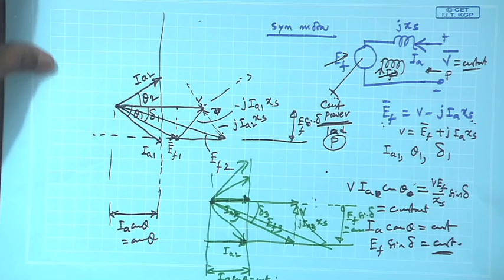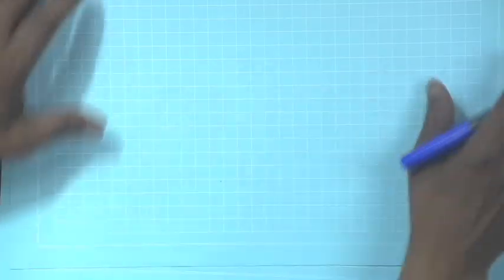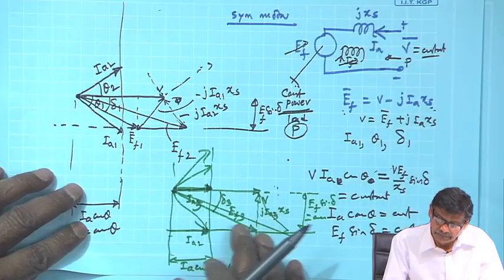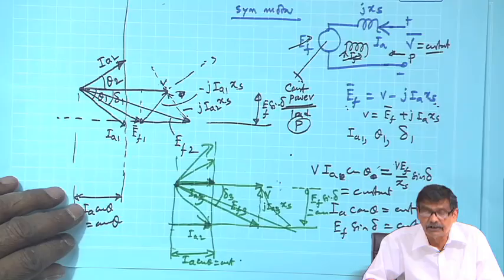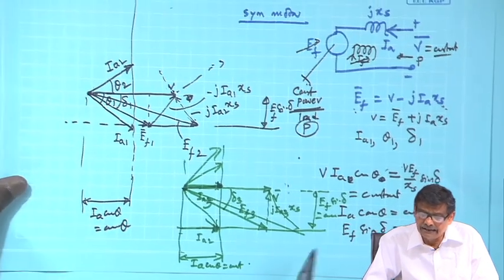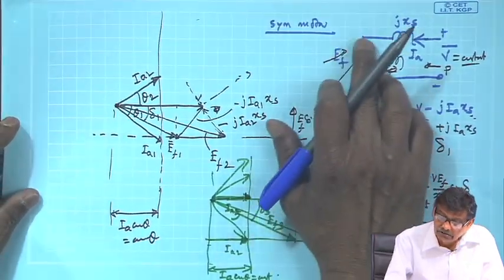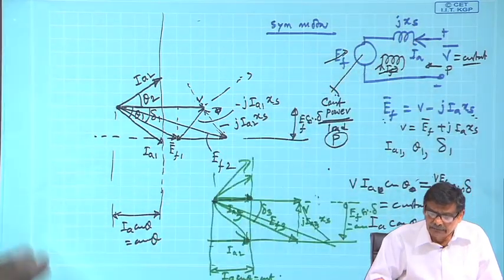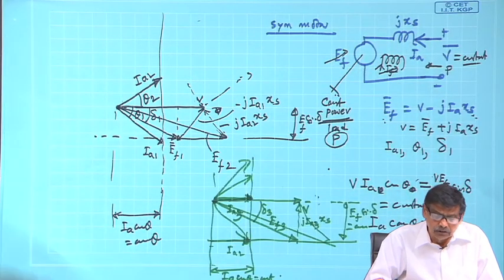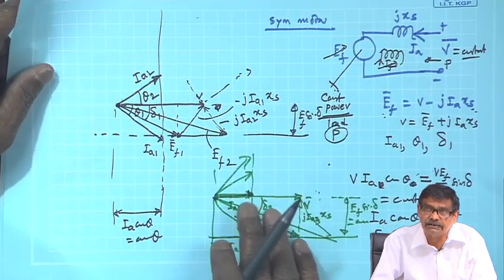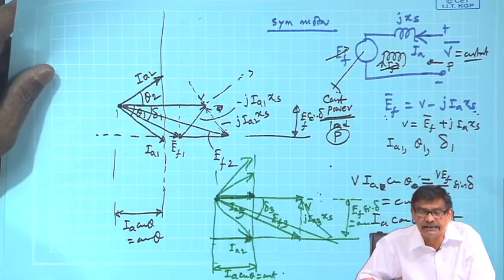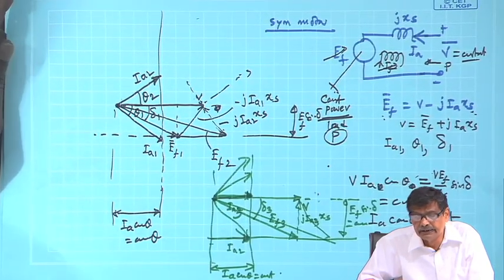So, once again for a motor I can draw a V curve. So, please make a practice of this one, because this phasor diagram, new operating point, how to calculate as you vary the excitation for a constant amount of power, and it can be done with also R_a included, that I will not pursue right now. Okay. Although I will include that in my note, you first get conversant with that. This simple case, when only X_s is there, R_a is much smaller than X_s.